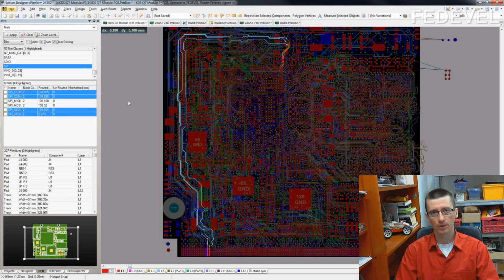And if all the interfaces which left unconnected are similar length, or the length is not important anymore, have a look on the number of pins and logically connect the one with highest number of pins. When you connect it, move to the interface with second highest number of pins. That's logical. I'm pretty sure you do it this way anyway.